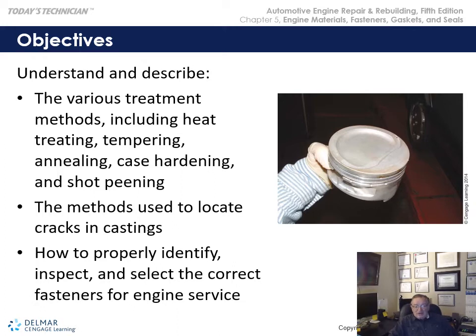Okay, there's also case hardening, where just the outside of the part has the temper to it. It's a heat process. And also shot peening, which will remove stress and also material. It's like a BB-sized aggregate that's shot against the metal and cleans it and also does stress relief.